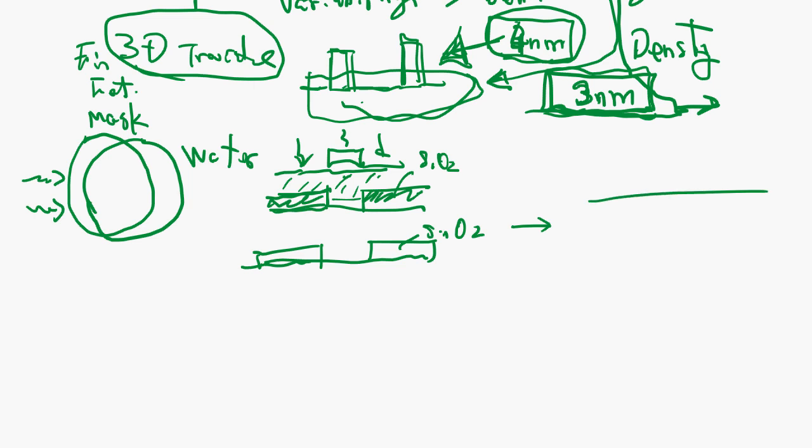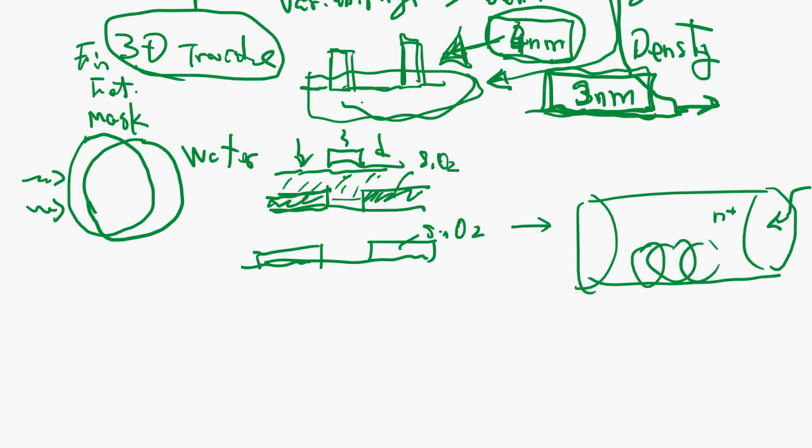In the diffusion process, you have a large tube and you put the impurity N plus, the many wafers here, and heat up, and it's a diffusion process. So it heats and the gas gets into the silicon, and it slowly diffuses this N into this way, N plus, right?